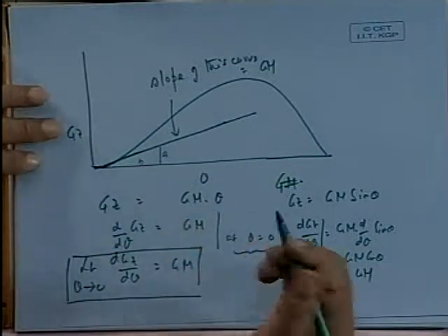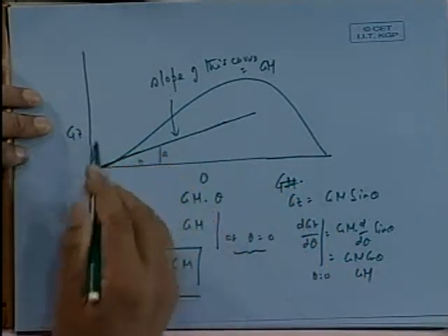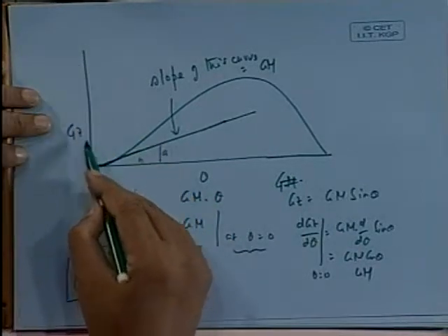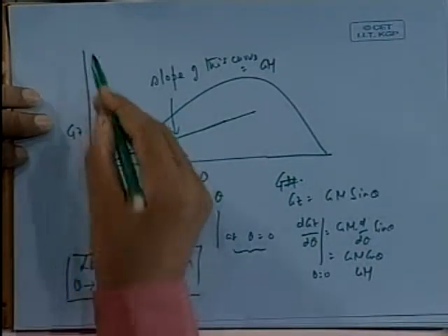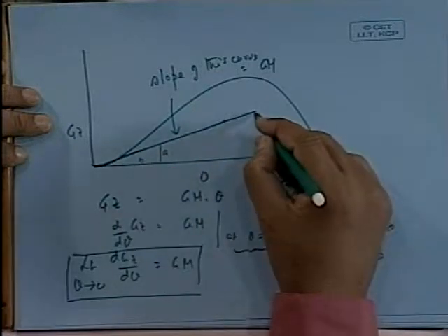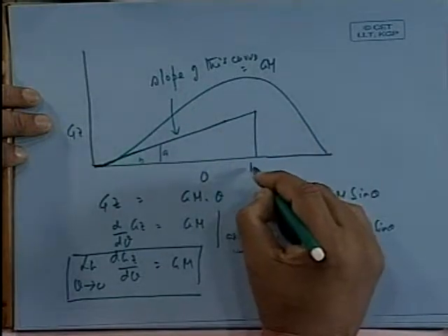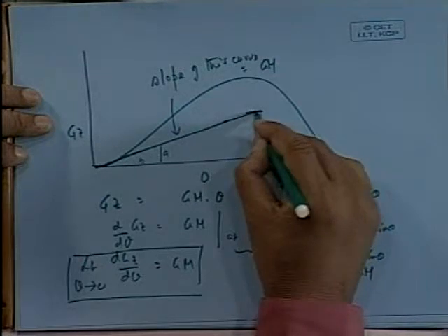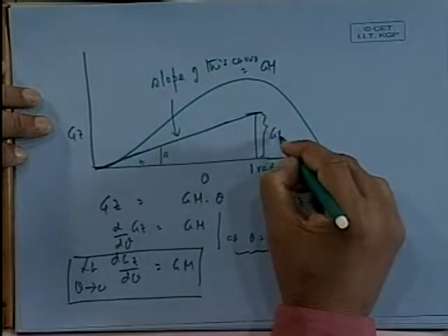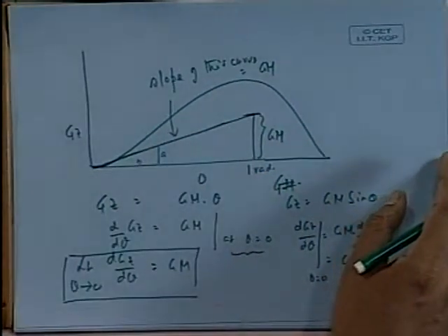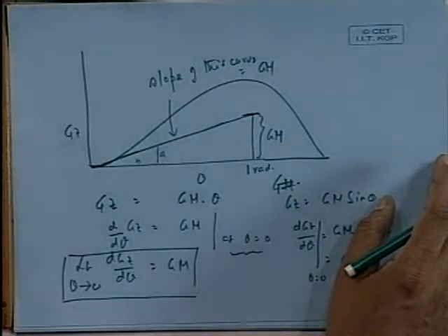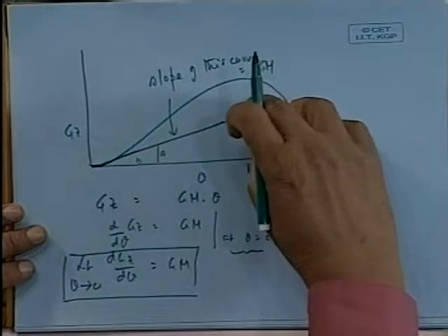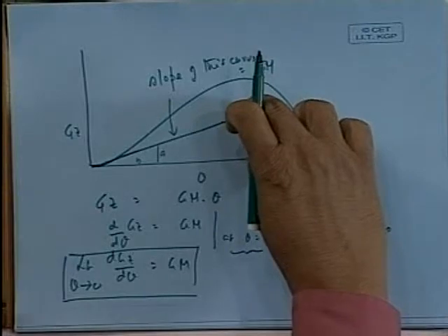So what people do is that, say, remember that this curve is GZ in meters, some linear length, 1 meter, 2 meter, whatever. So if you make B as 1 radian, then this distance directly give you GM. Most people will tell us that from the GZ curve, you take a slope there and take 1 meter radian, you get GM, as if this is absolute.